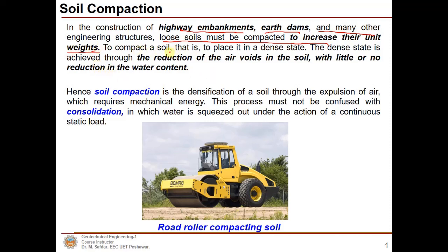To compact a soil, that is, to place it in a dense state, the dense state is achieved through the reduction of the air voids in the soil with little or no reduction in the water content. So in compaction we are removing or reducing the air voids in the soil. Hence soil compaction is the densification of a soil through the expulsion of air, which requires mechanical energy.